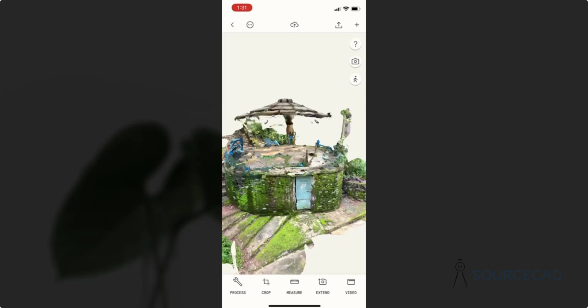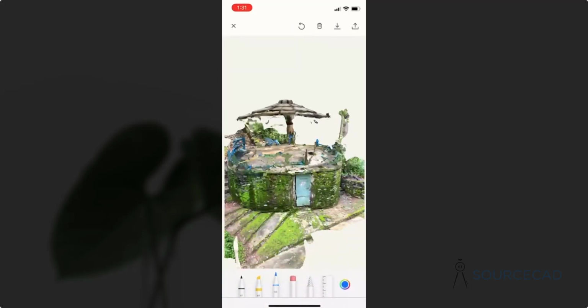Now let's talk about adding markup, and for that click this camera icon. Once you have clicked it, it will take you to this. Here you can add markups using different options. So you can use pencil, pen, highlighter and things like that. In this case, I've started by selecting this highlighter, and after selecting it, just mark the areas. For example, here we don't have the poles or the pillars, so I'll mark it, and I'll also use this pen to add an arrow, and I'll add a text as well, like this one. So pillar, so they're missing, so I'll maybe just add it like this.